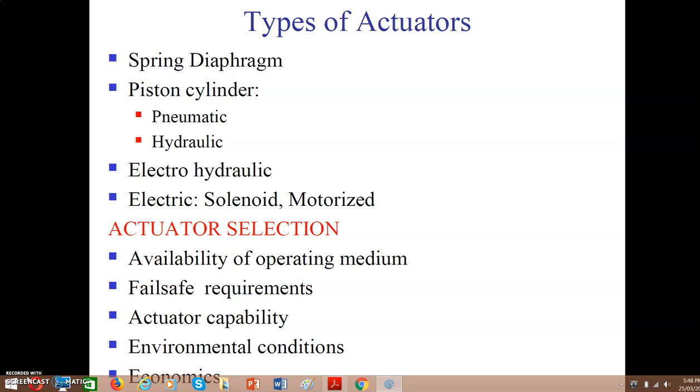That means the valve closes and opens due to vertical movement of the stem. These types of valves are suitable for high pressure drop applications. Now, as the fluid passes through the control valve, there is a pressure drop across the plug. Since the movement of the valve stem is vertical, in case of sliding stem, the pressure drop that is created across the plug does not affect the movement of the valve stem.